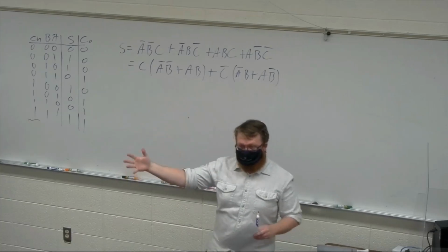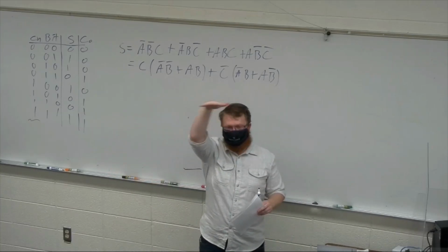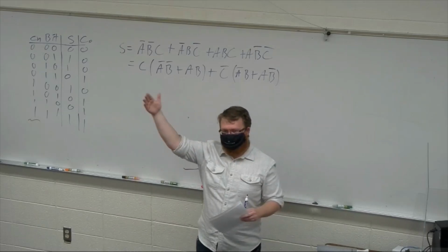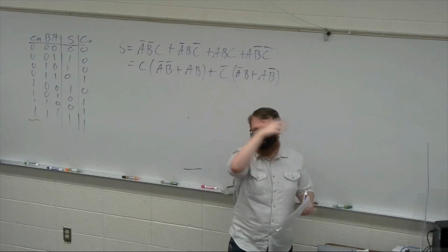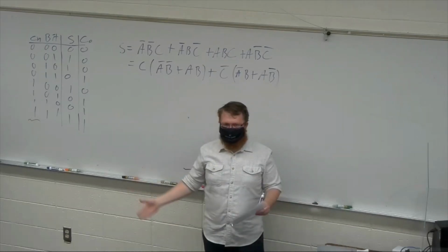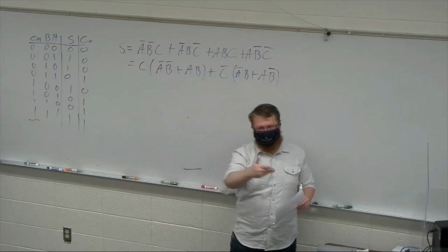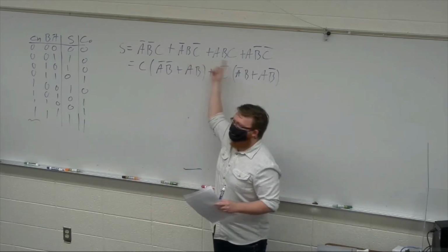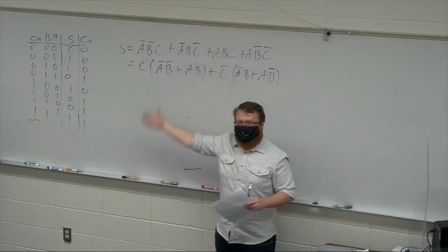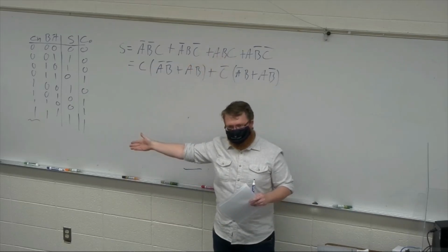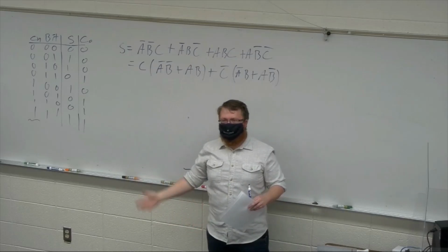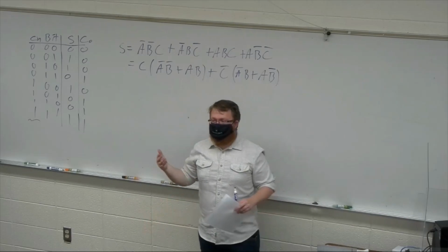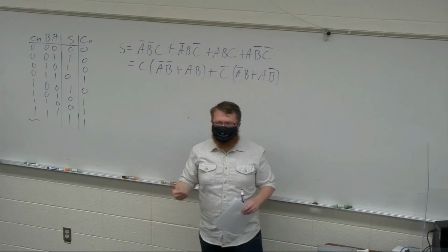And then the downside is that when I upload new inputs, it can't know the answer until the carries have carried all the way through. So if I have 32 bits that I want to add, I have to carry through 32 carries. So if I have 2 gate delays, say in a full adder, which is possible, right? This would just be 2 gate delays. Then you would be in a situation where you have 2 times 32 delays. And so no matter what your clock is, you can end up in a pretty small limitation for how fast your adder can go.